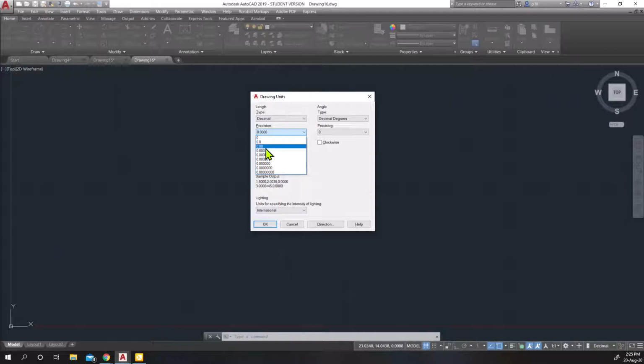In other words, as we draw, we have to tell AutoCAD, I want this to be 2 inches or 3 inches or 27 inches or 58 inches. We can input the precision by selecting one of these precisions. Usually it's going to be 2 to 3 decimal places. I would say let's default to 3 decimal places. That's a good default to have.